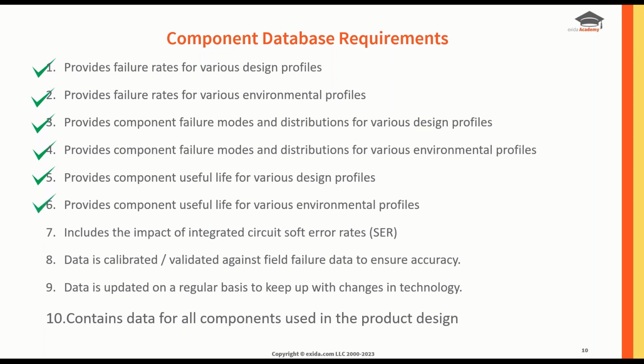There's no point in picking a component that has a useful life of maybe 3 years when you're looking to design a product that you would hope to be up and running in use for 10 years, let's say. So straight away you've a weak link in your chain. But having a good database and having useful life data enables you to straight away decide, will this component be the downfall of our particular product.